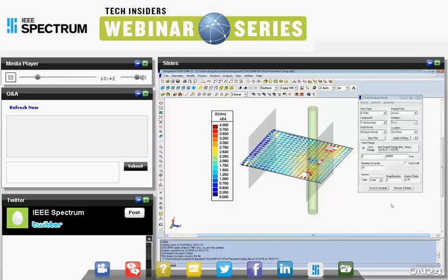So if you look at it and you see the electric field plot that is produced, you can see that the field is, of course, reasonably uniform in between the two plates, but there's fringing effects, and there's a very high field at the corner, so a user range was selected to prevent that from swamping the whole presentation. But you also see some bending and color changes around the rod itself.